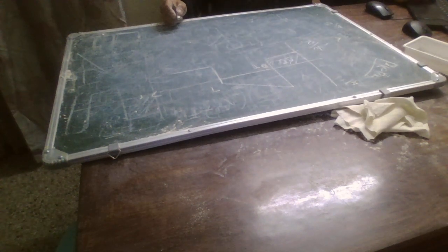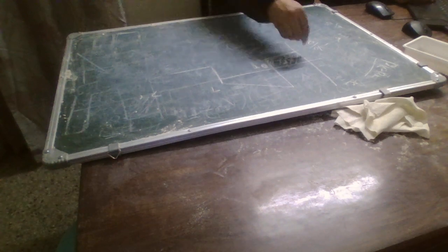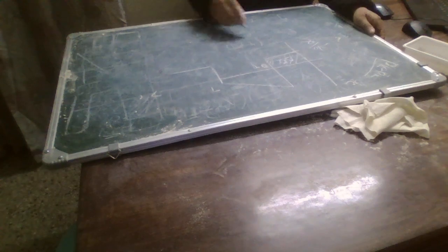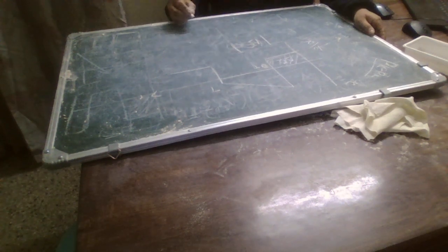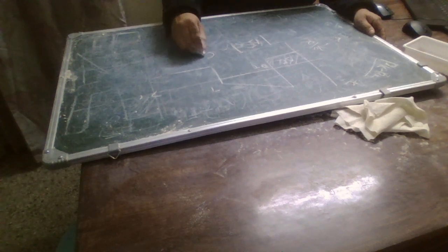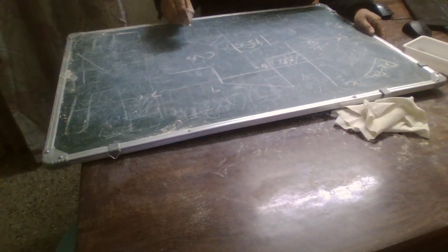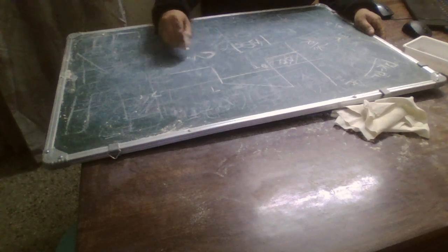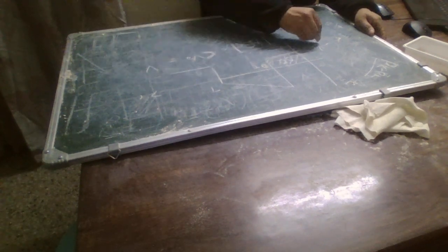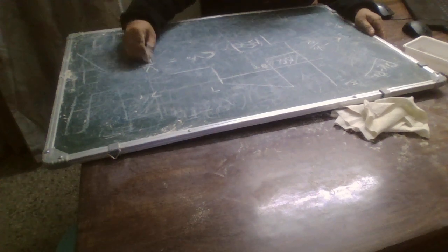I can very easily calculate the peak to peak ripple using this graph only. If I take the modulus of delta Q, it would be C delta V naught, and here the current would be equal to V naught by R.